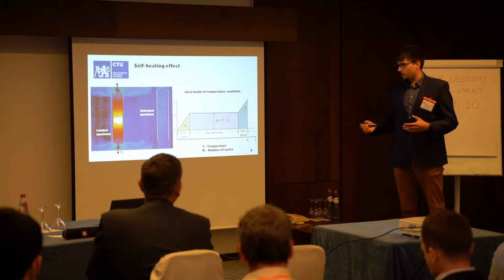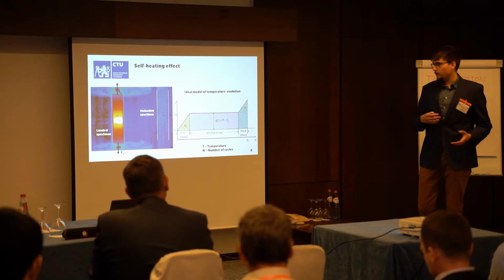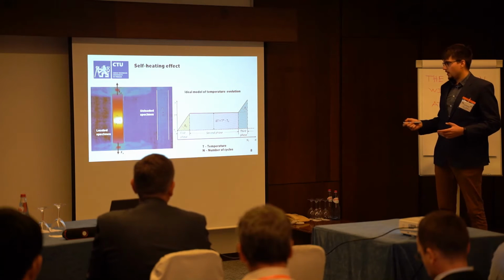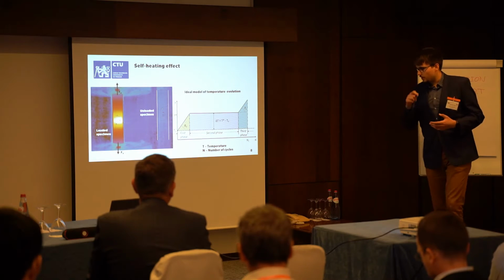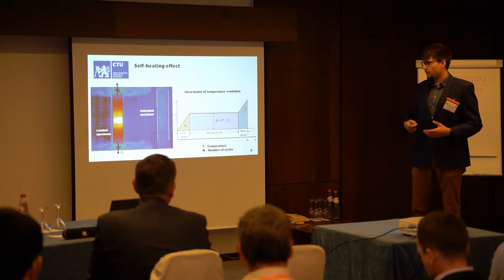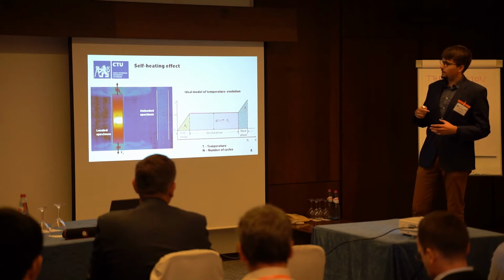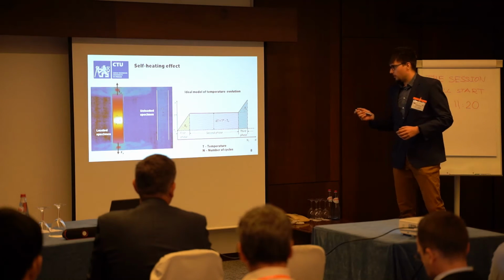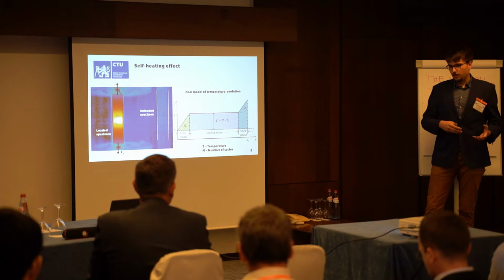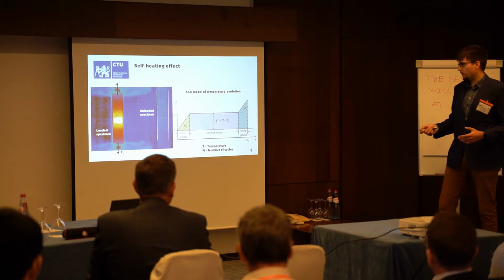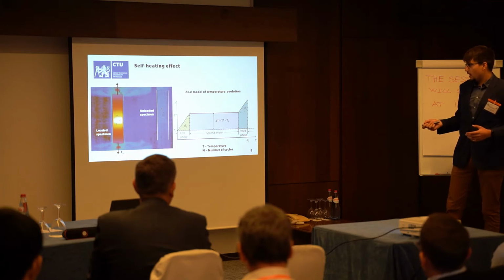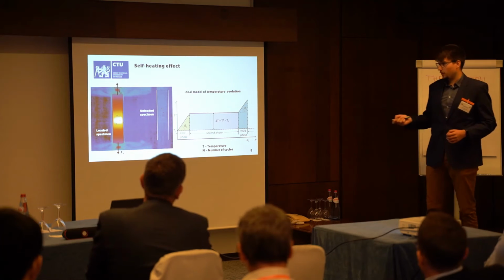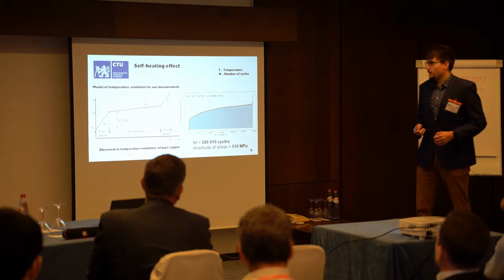And the main motivation here is to use an additional parameter for the fatigue experiments, which is called the self-heating effect. The self-heating effect occurs during the fatigue loading with the amplitude of load, and you can see that it develops in 3 phases, as you can see here. The first phase can be characterized by an initial incline, and the second phase can be characterized as a stabilized temperature. And the third phase can be correlated with the crack initiation, and it leads to failure, as you can see here. But this is the ideal model, which wasn't really working in this case.